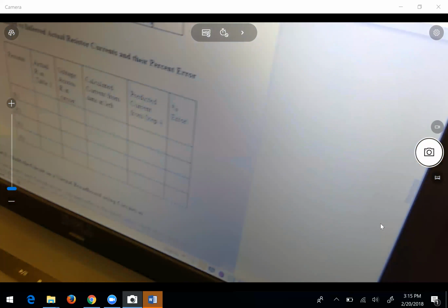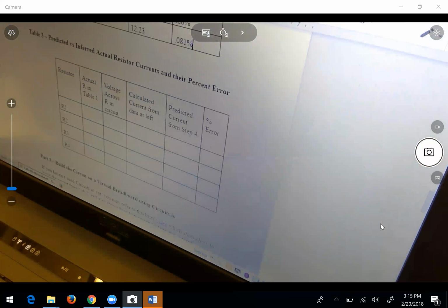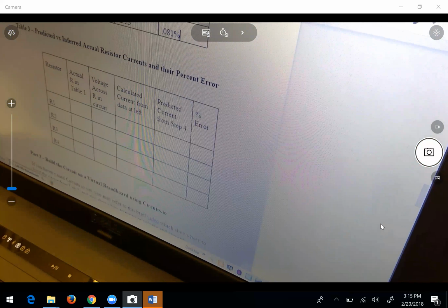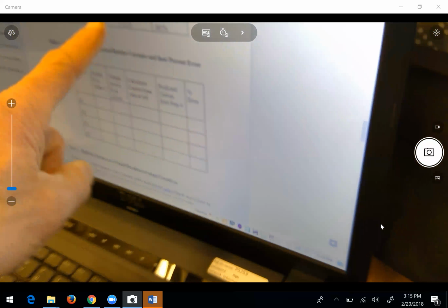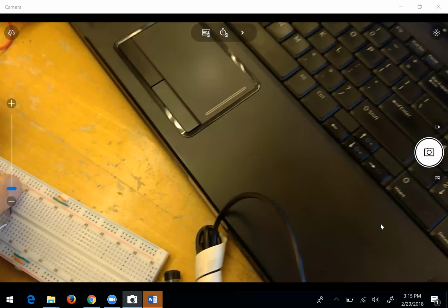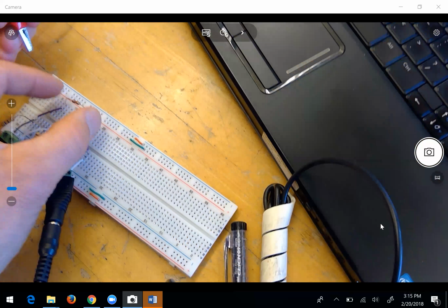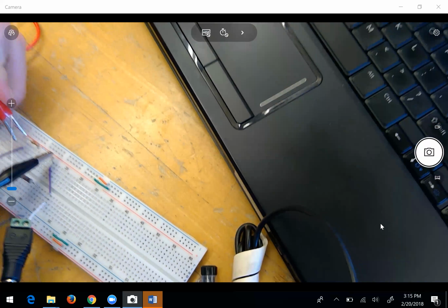But to measure it, you're just going to calculate. You don't have to measure the current, or to measure the voltage. So let's do it for R4. If you've got the node voltages up here, you could measure it by moving your voltmeter so it's going across there. Put the red here and the black there. Yeah, you could, and you're going to get the same number.